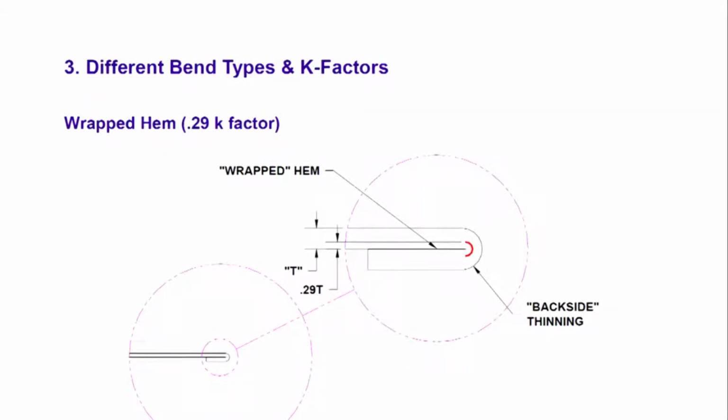So, we see here a completely bent over 180 degree bend. Can we actually make it flat? In some conditions, yes, depending on the softness of the material. The reality is that usually, though it is not easily visible, a small gap will be left there. In this case, it is given approximately 1/4 of the thickness, a little over 1/4 of thickness.